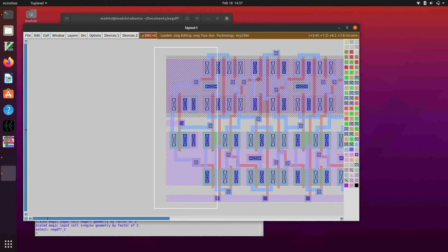But instead of having to do that both in the right-hand edge of the cell and the left-hand edge, for the sake of making these 2 inputs one input, I've elected to make them be 2 separate input ports, and I'm taking care of generating the D bar with this end cell that I'm putting on the left-hand end of my shift register. So here I have this inverter.